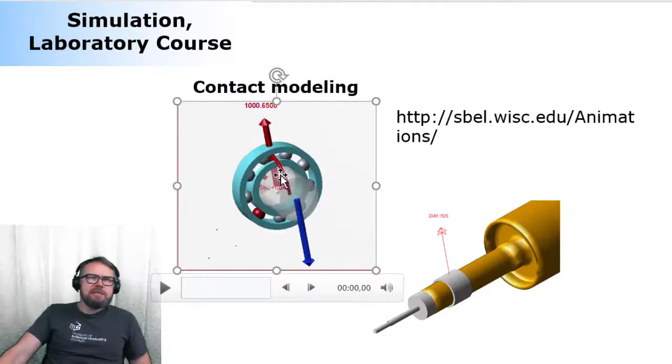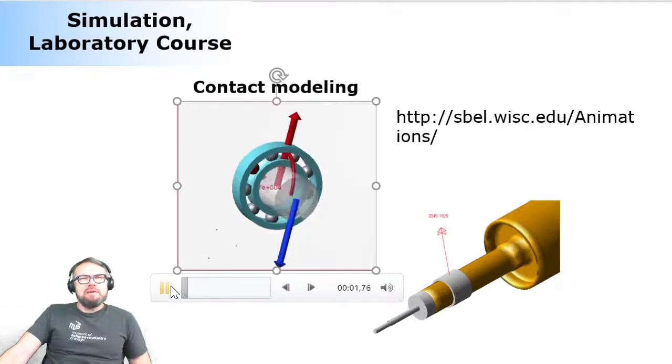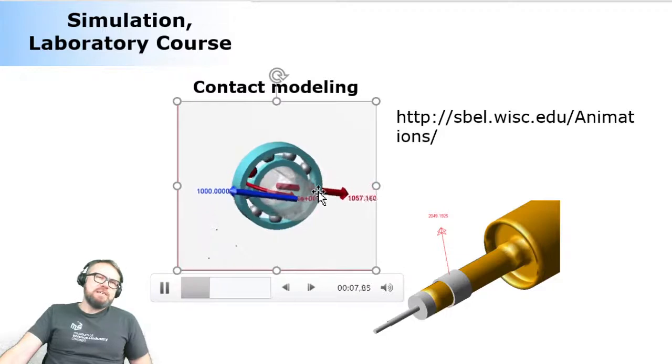I don't know if you see this clear, but there's a short shaft here, and then there is a force hanging at the end of the short shaft, and you can see that the reaction force here is fluctuating. And why is that fluctuating? It is because of the nature of the ball bearing. Because in a ball bearing, the stiffness depends on how the ball is positioned.